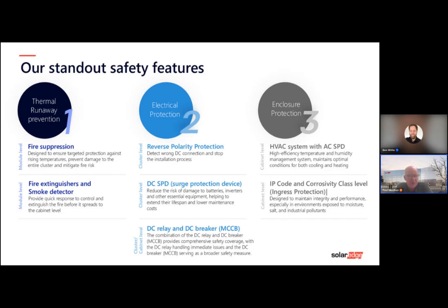But in the main, I would say, in the UK it's not a bad idea to put some sort of GRP protection, so you don't expose it directly to driving rain in very inclement conditions, if that's likely to be where the installation is. So that's always a good idea. But the IP54 will protect the unit to the IP54 regulations and standards.